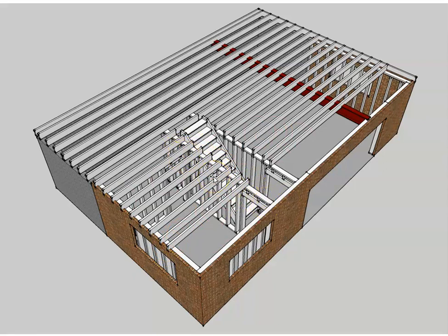So in this exercise, it's definitely important to understand the difference between load-bearing walls, exterior ones, and interior ones. So there are 4 here. 1, 2, 3, 4. Those are carrying the loads up from the roof. The snow on the roof has to make its way down, and it's going to make its way through these joists, and then the loads will make their way down these walls.